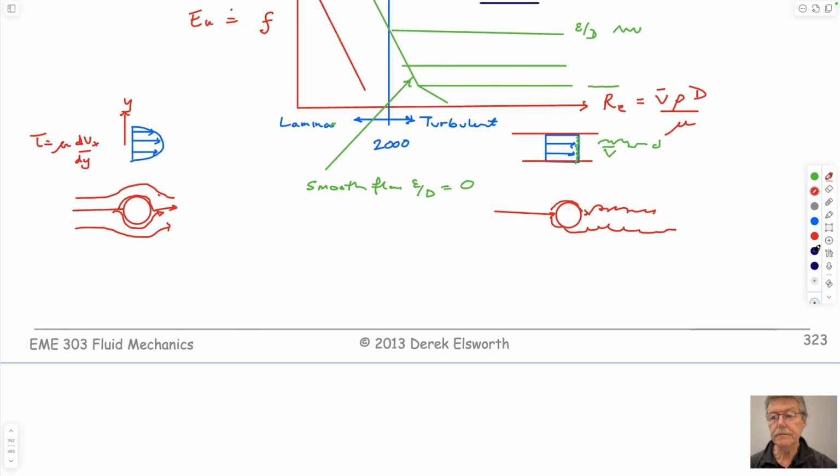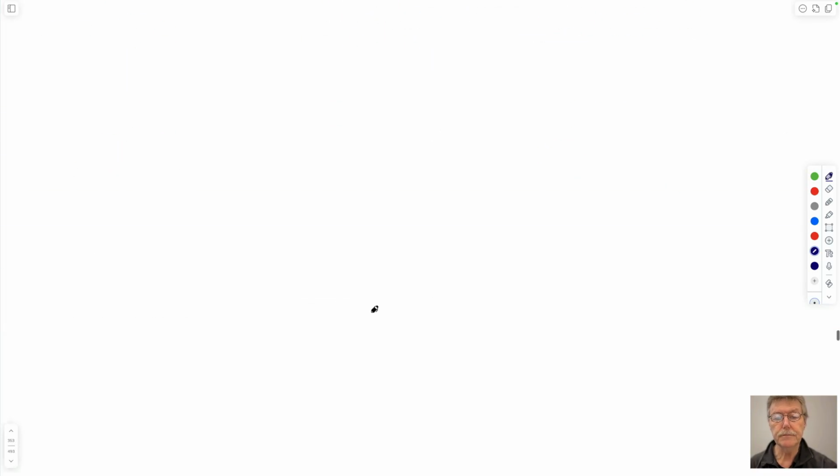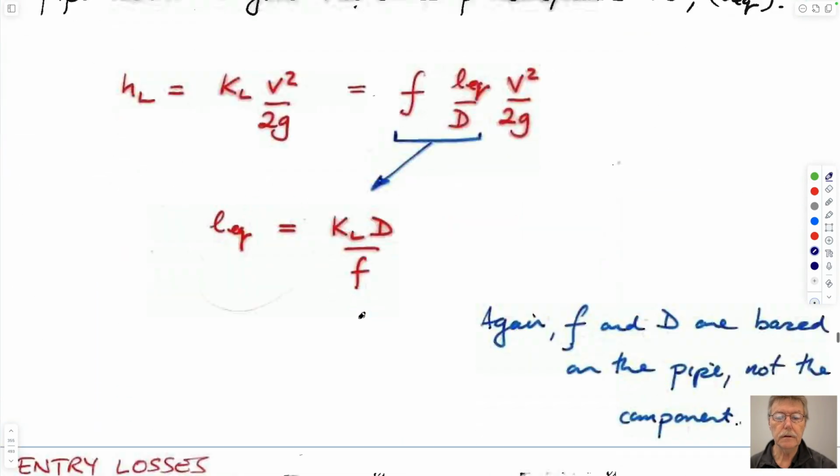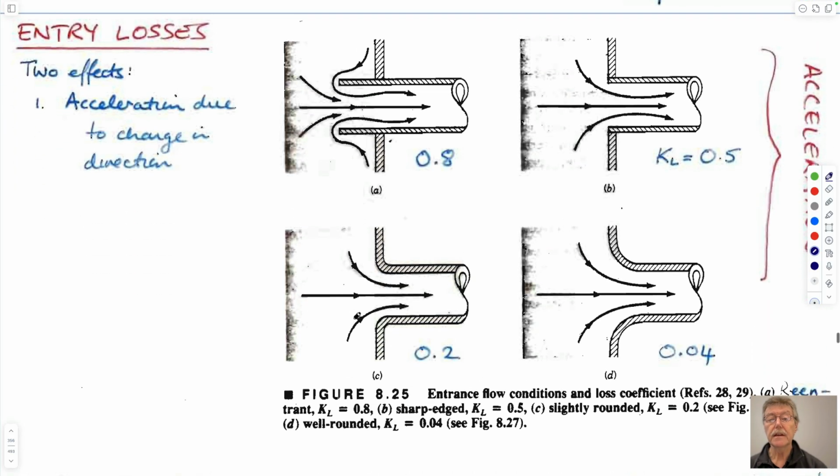We'll come back and do a jet lab soon, but let's just zoom through this. This is the idea, that when you have fluids going from zero velocity here to accelerating to some other velocity here, there may be a loss from the geometry that you have. We can calculate that head loss as a loss coefficient multiplied by the average velocity in the pipe squared, or the velocity head, I guess it is, right? This is the average velocity in the pipe, so it'd be the velocity here, not the velocity before it goes in, because that might be zero, right, along a streamline.